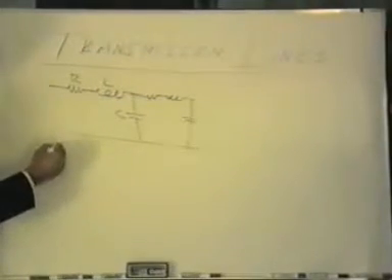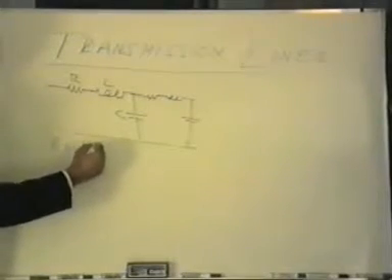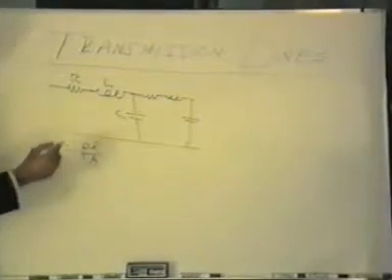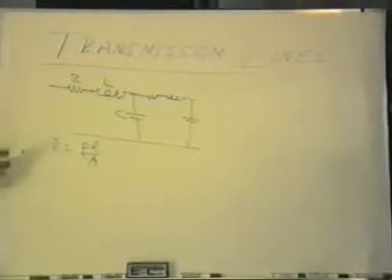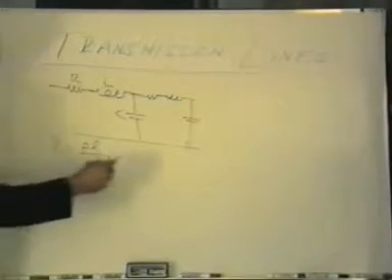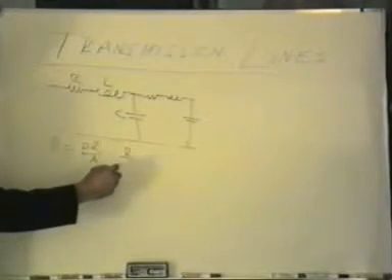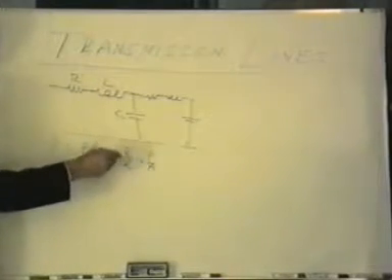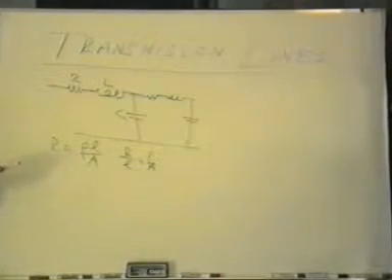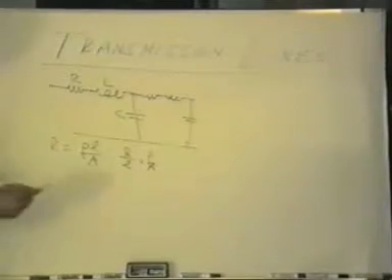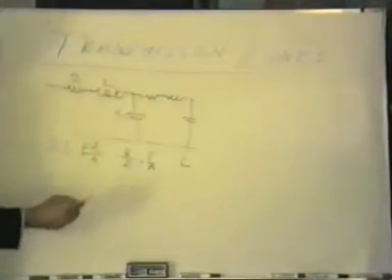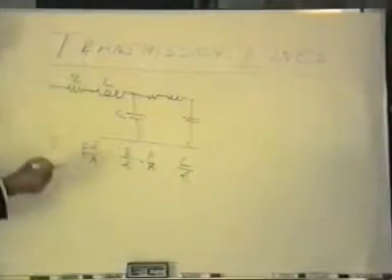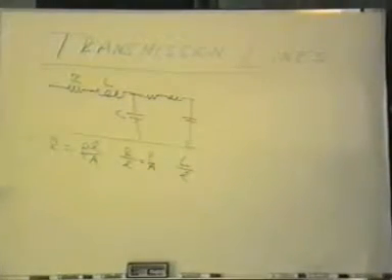Now, resistance is given normally by rho times L over A, where rho is resistivity, L is the length of a piece of a conductor, and A is the cross-section area. Very often in transmission lines we'll talk about R over L being simply rho over A and call that the resistance per unit length. Similarly, the inductance is often specified as henries per unit length, and the exact formula would depend upon the type of material, whether it's non-magnetic or magnetic material being used for the inductance.